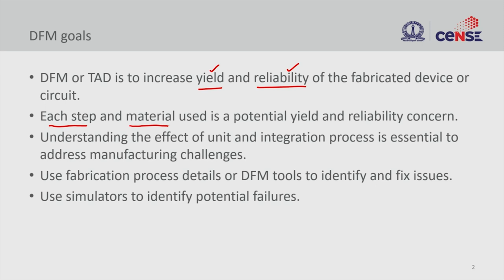So when we say each step, processing requires multiple steps, right? So we saw, for example, for patterning you need optical lithography followed by, let's say, dry etching. So optical lithography involves photoresist, illumination, development, and so on. And dry etching requires exposure of your material to plasma, right? And for instance, if you want to fill a gap, you want to deposit dielectric material, let's say silicon dioxide.